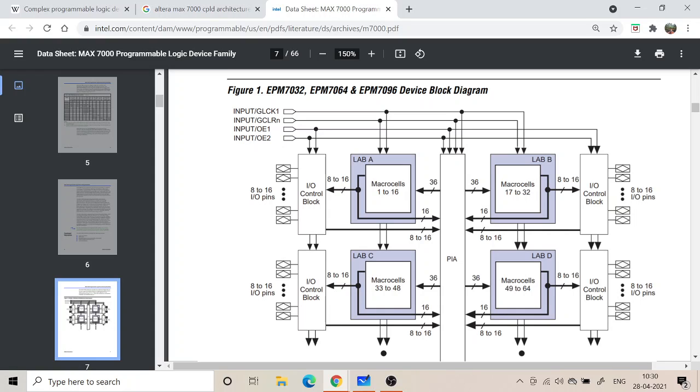Okay, but if you take synthesis software from say another company like Xilinx, and then you generate a circuit, it will work for their chips. Okay, it will not work for say Intel's Altera chip. Okay, so that's the thing. So you need to have corresponding synthesis software if you are going to plan to implement or configure your circuitry in an FPGA or a CPLD chip.